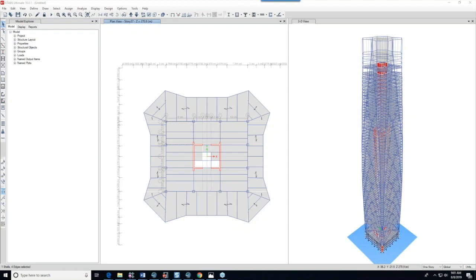So we're going to just start with what is a diaphragm constraint. And I think people using the software understand the difference between restrained joints and constrained joints. So we're really talking about constrained joints. And if you think about the typical body constraint, you can think of two joints that are connected together rigidly, and those two joints in any part of a model are going to translate and rotate as if they're locked together.